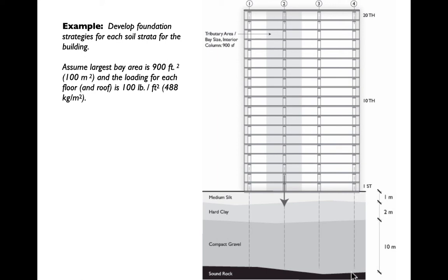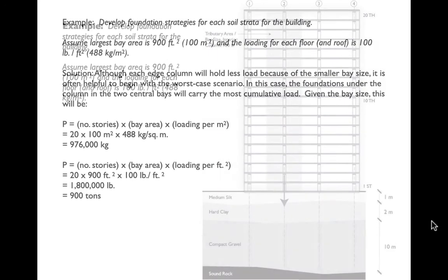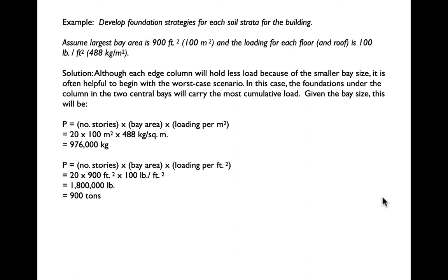But we would like to find the simplest foundation system that we could. If we could put the building on medium silt, we would love to do that. Odds are we're going to have to go at least to clay or gravel to get a decently small foundation size.